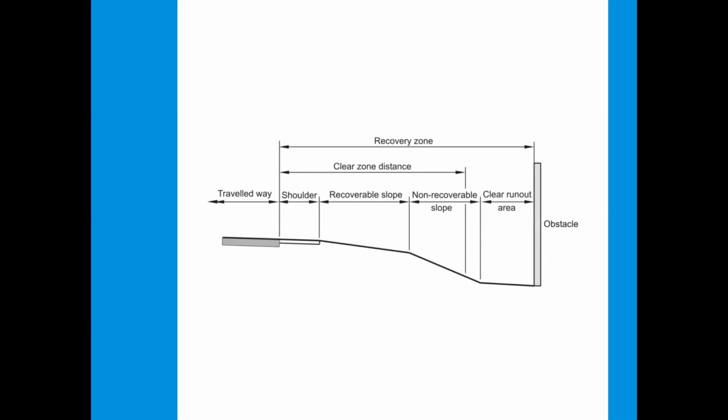Common types of poles include slip-base poles, impact-absorbent poles, steel fragile posts, aluminium fragile assemblies, and wooden fragile posts. A slip-base pole shears on impact, with the pole landing close to the point of impact. Impact-absorbent poles crumple and bend around the vehicle.